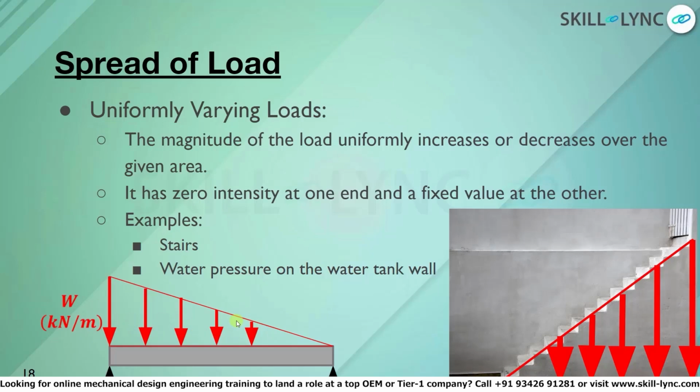Uniformly distributed loads and uniformly varying loads are difficult to resolve when they are used in large systems. Thus, they are usually converted to a point load. A point load is an equivalent load that is applied to a single point. This can be determined by calculating the total load over the object's area and attributing the entire load to